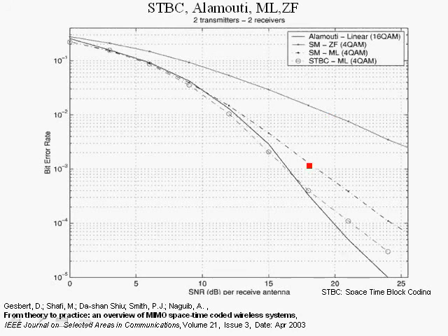Let's take a look at this curve over here. This is for the spatial multiplexing using maximum likelihood, again with 4 QAM. We see that the maximum likelihood decoder for 2x2 MIMO greatly outperforms the zero forcing MIMO equalizer. And the fact is that as we increase the signal to noise ratio, we get a steep decline in the bit error rate. Now, this is very important.